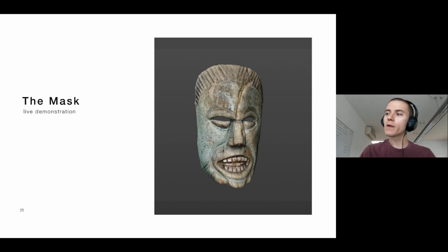So I would recommend, even if they are really flat with no deformations whatsoever, try to look for surfaces that have at least some kind of texture or structure that gives the surface contrast. Because if you have something with some kind of texture, even if it's flat, the software can recognize that and build you a flat surface.